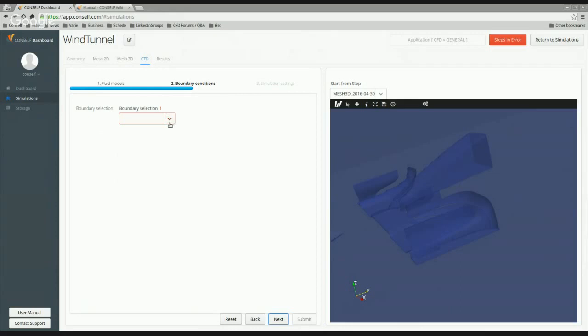and set up the boundary condition. For each boundary, we have to prescribe the behavior of the boundary from the fluid dynamics point of view. Let's select body, and the default is the wall no slip. That's okay for the body, as well as for the wing and the other wing. Same thing for the Z axis at the minimum, so the ground is a no slip too. Then X-min and X-max are the lateral walls, and we can use the symmetry boundary condition for both.